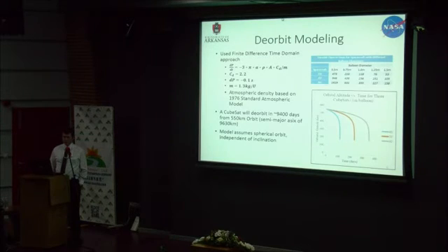What if there is a leak in the balloon? Would it inflate? If there's a leak in the balloon, I think it will inflate, and there's a couple reasons why. First, the pressures we're talking about are very low in order to inflate it. So if you have a low pressure, you have a low leak rate. Even if we do have a leak, we can generate far more gas than we need to inflate. So even in the presence of a leak, I believe we can still inflate it. Then over time, if we have a continual leak, we have the option to keep inflating. So that's my answer.